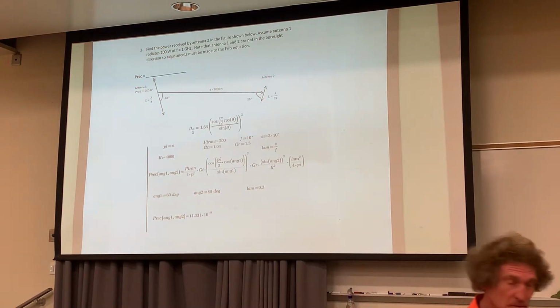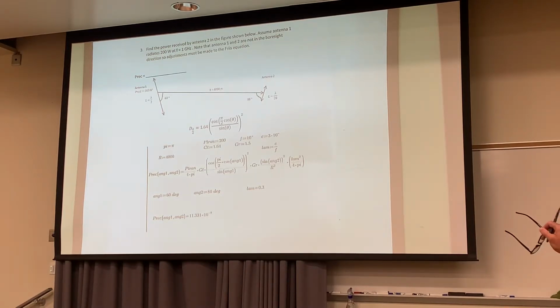Come on, guys. If you work these problems frequently, several times, and then when you review you just do them one more time, it usually sticks with you. And if you forget, always go back to the basics. Transmitted power over 4 pi r squared is the isotropic power density. You multiply it by the gain, it sharpens it. Now you have the average power density flowing. Now you just have to catch it with the second antenna. How much do you catch? It's always lambda squared over 4 pi times the gain there. So that's how I do these problems in my head.